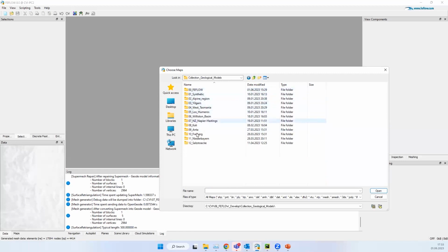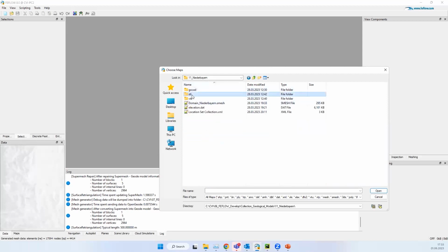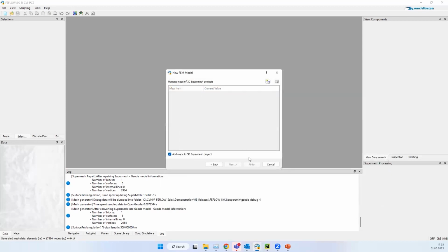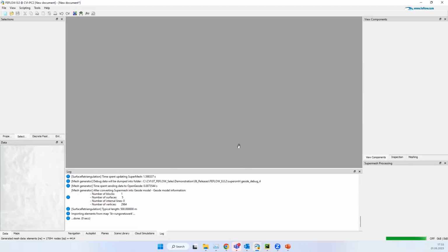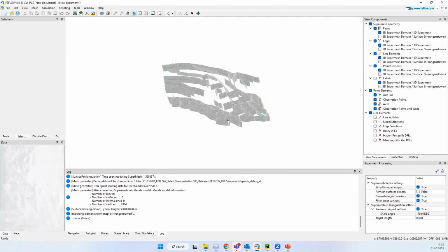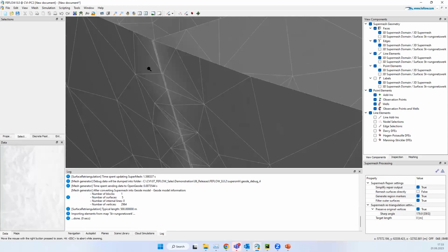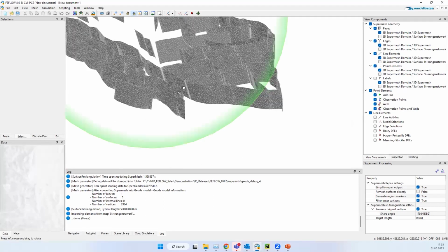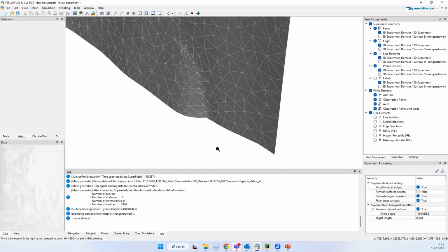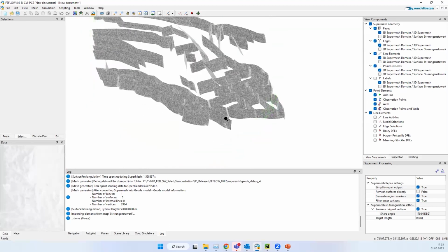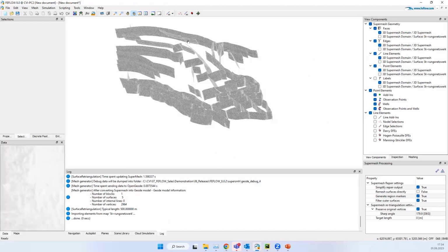You can see all the different geological models that I have been testing. Nearby STL surfaces. So we can add the faults. That goes really fast because it's just one file. You see that it's okay sometimes, but in some cases they are not meeting well here. This will throw a self-intersection error, and this one probably too. So you can call some remesh method.